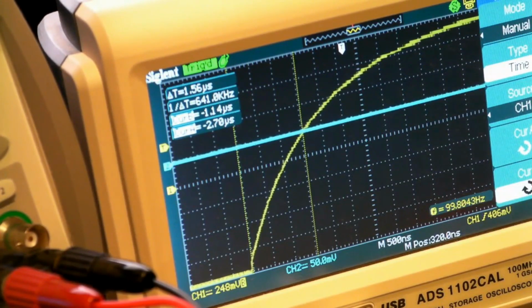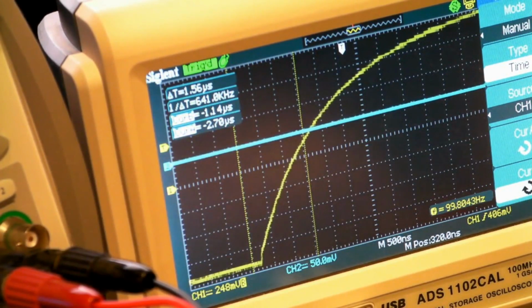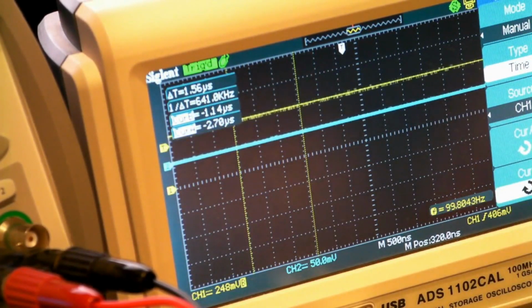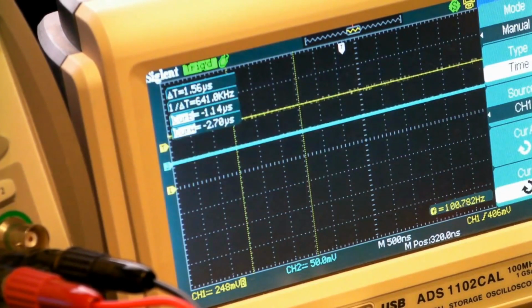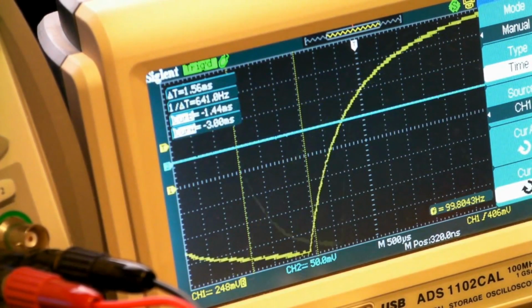Anyway, so the way to now bring in the capacitor that we want to test is I'll simply connect it to the other side of the capacitor now, and you notice that this has completely changed the waveform, because it's way, way slower now. So if I reduce this down, we'll see that we basically have the same kind of edge.